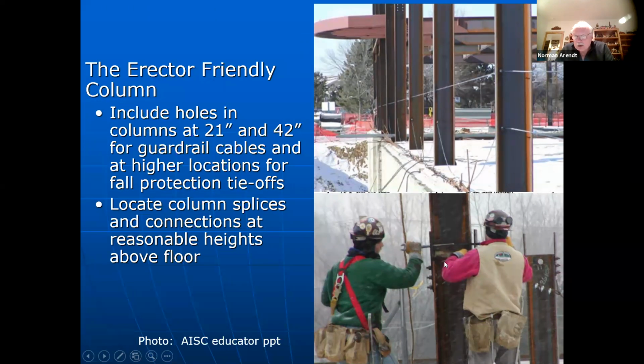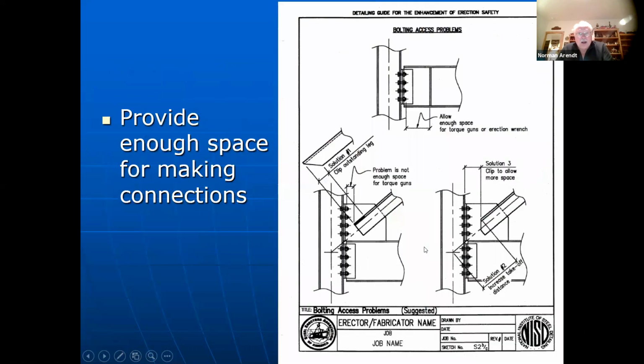And also locating the splices at an elevation where you're not reaching overhead, but we're working no higher than shoulder height for the connections. I always like showing this one, which provides enough space for making connections. I was working on, I think it was Tower Drive, although it might have been the Arrowhead Bridge tied arch, many years ago in my early years.